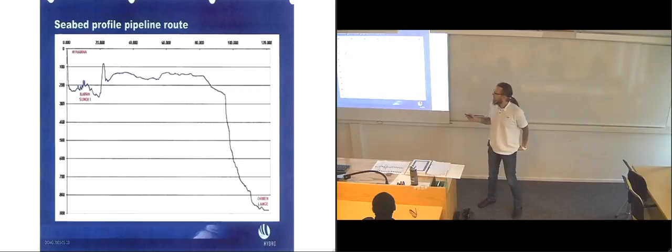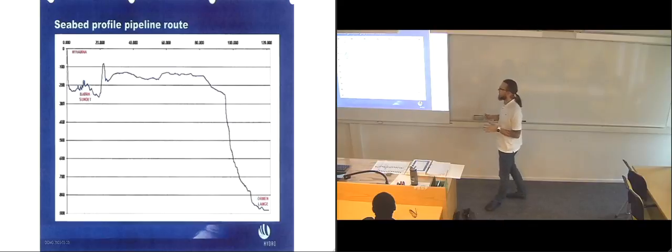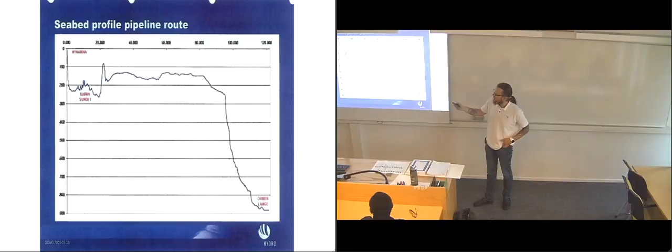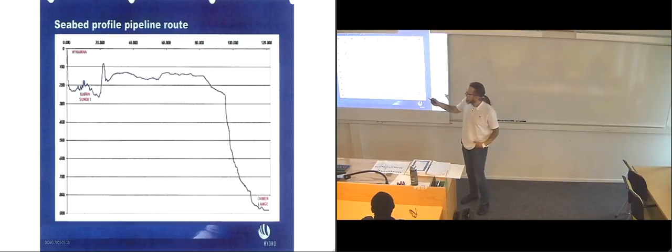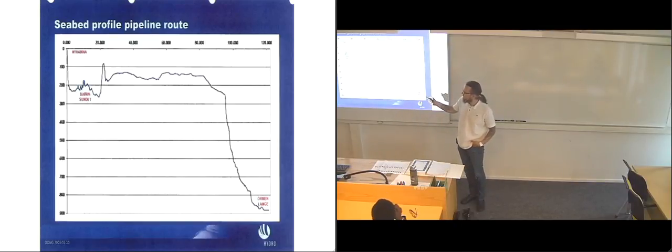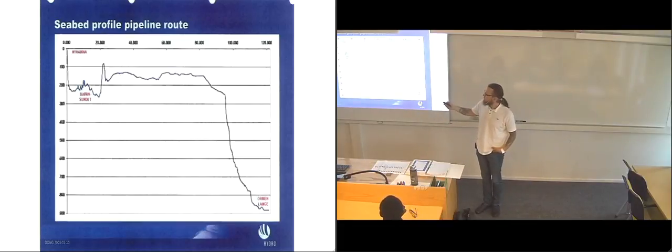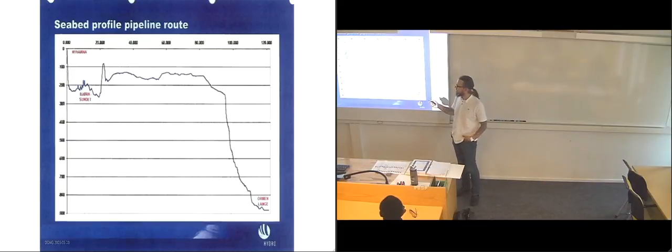Here's a map of the seabed profile for the pipeline route from Aukra and out to Ormen Lange. So in here is the shore. Here we have Nyhamna, which is the land. And then you have Bjørnsundet, which is very close to land. It's fairly deep, so it's easy for ships to pass. It's another problem. You see it's all the way down to about 200, and even deeper. And you see it's really, really jagged here. So it's pretty difficult to place your pipeline here.